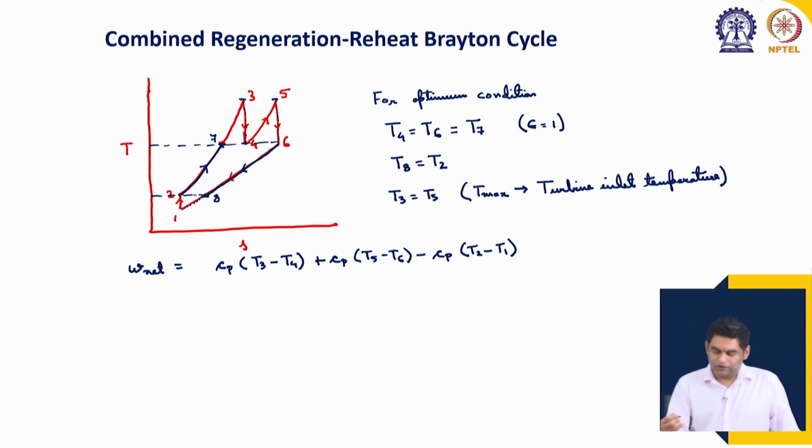So, this is the net work output and this is similar to the case with only reheat, because here regeneration does not change the work output from the turbine, neither does it change the work input to the compressor. So, the net work output remains the same as the reheat cycle.